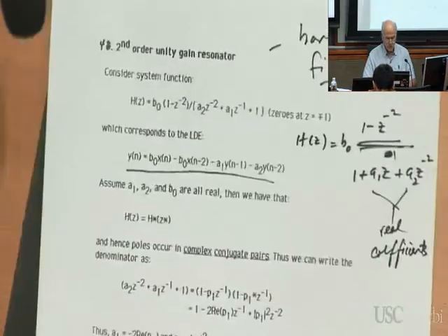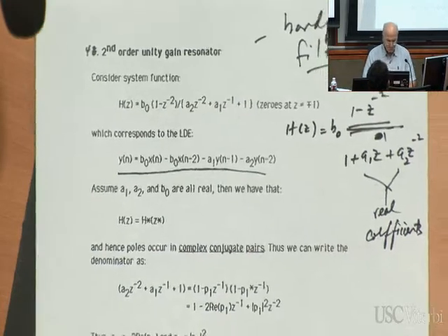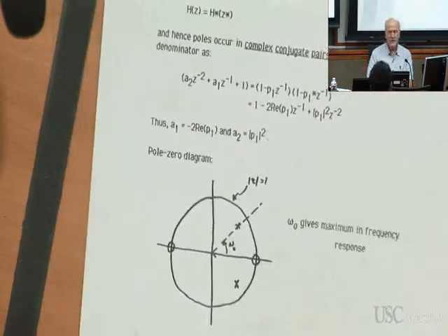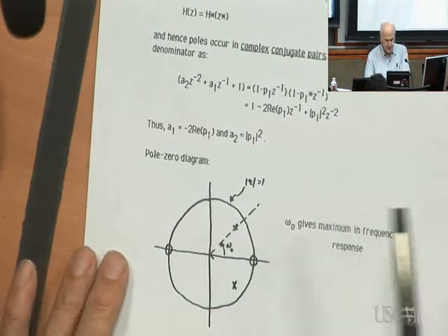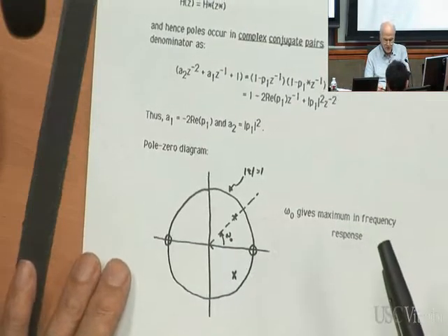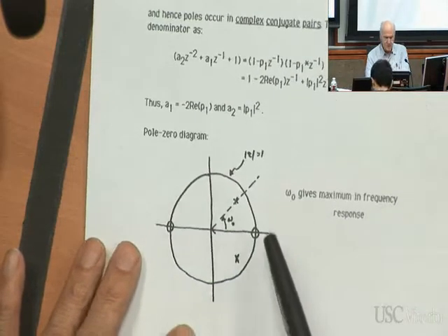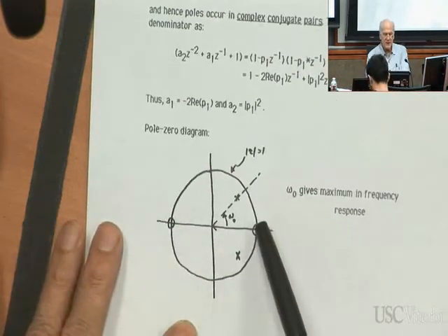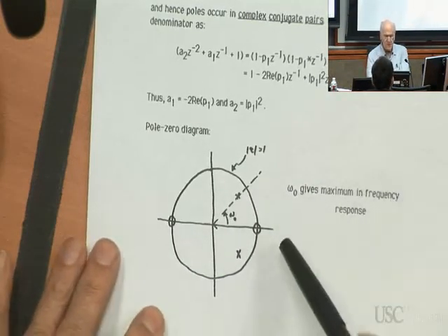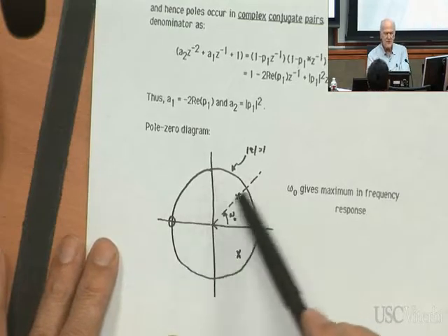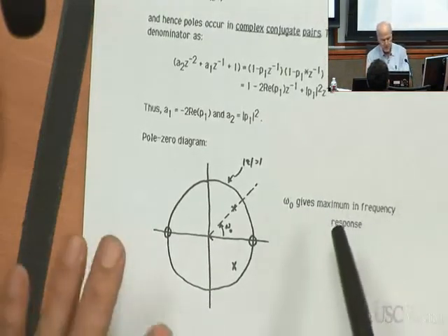So I went through and wrote what the pole representation would be. I won't spend much time on this particular filter example since we don't use it, but if you plot out the poles and zeros, you will find that you have two zeros at 0 and pi, and then you have two poles, of course, inside the unit circle, and if you draw the circle enclosing that, you will find that, as usual, it's a stable filter.